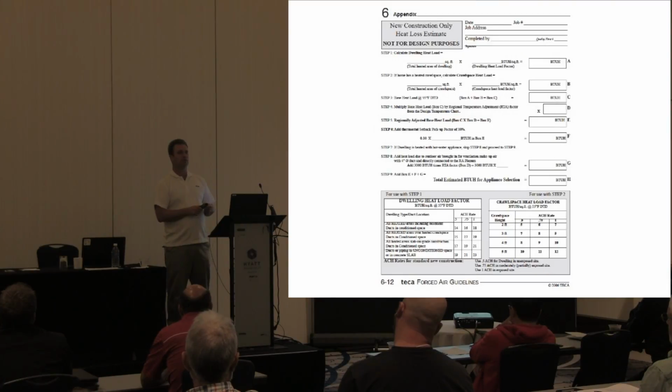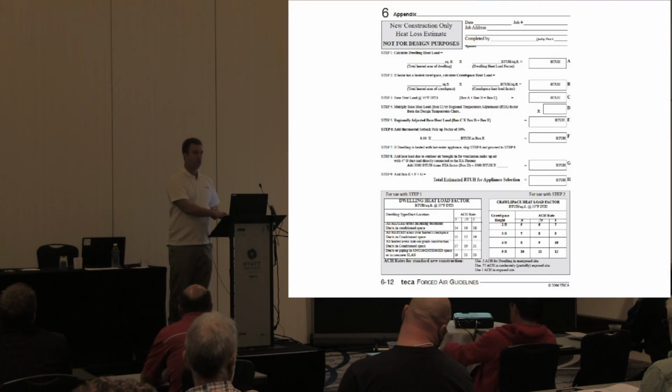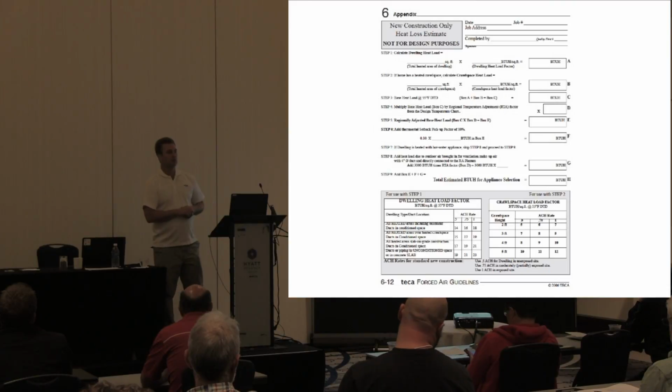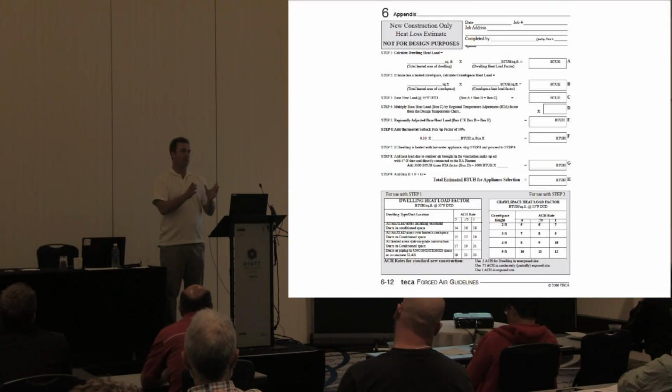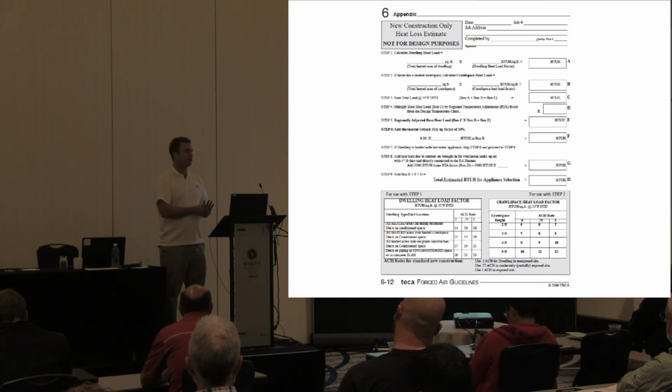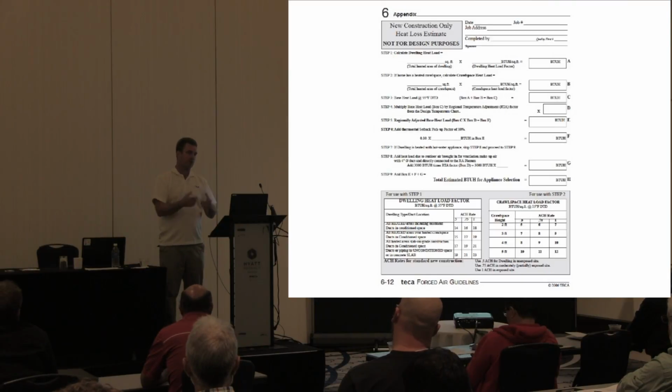Do I understand then that possibly 2 zones would be a good idea, but going 3 or 4 is stupid? My experience has been about 1/3 capacity is about the lowest I've gone, and even that, you're getting into the potential for a bit of noise. It's comfortable, but you're getting into comfort issues as far as the noise level goes. Most of the people willing to spend the money to put that in would be better served splitting the house into 2 furnaces and then splitting those 2 into 2 zones or something like that, if they really want the comfort level.